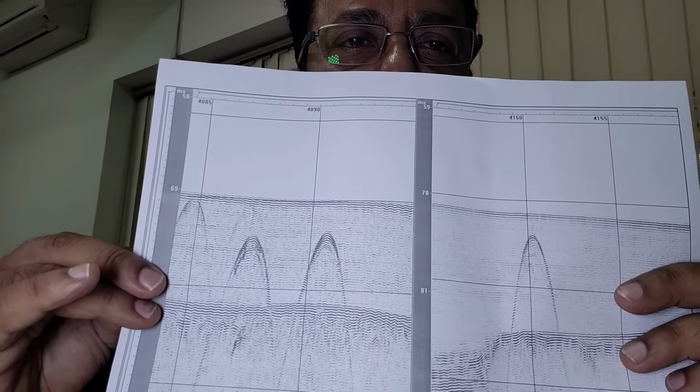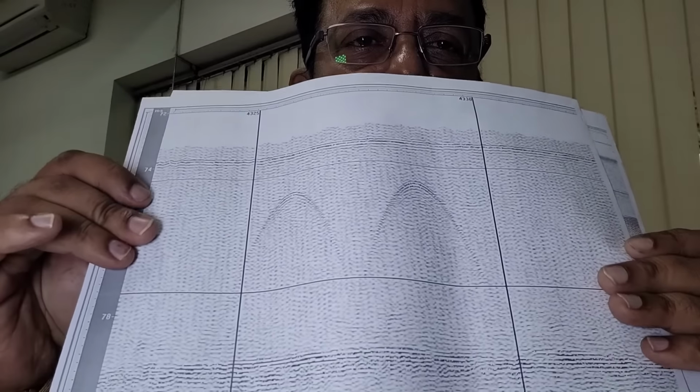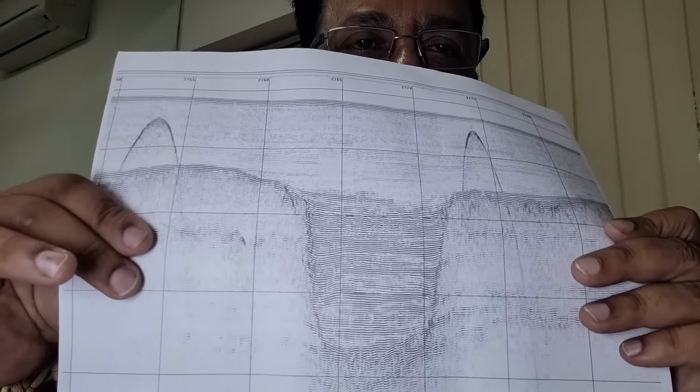Have you seen these pictures before? They are a graphical representation of a pipeline underwater. We use a system called a sub-bottom profiler that sends acoustic pulses to the seabed. Some of the energy will bounce off and most of the energy will penetrate and continue to propagate. When the acoustic impedance of the adjacent strata changes greatly, the acoustic pulse will be reflected strongly. The pulse reflection and refraction will happen at the interface of the different contrasting media.